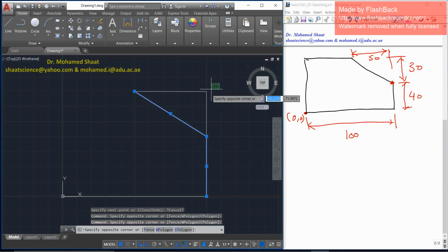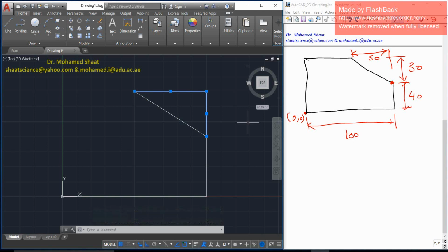But how about these other two lines? These are two extra lines that I just drew, but I don't want them. They shouldn't be included in the drawing. I used them to locate a point, so now you have to remove them. How can we remove a line, or any object? On AutoCAD, simply select the object and press delete. Directly it will be deleted. So now we have this vertical line and this inclined line. Then you can simply draw the horizontal line.